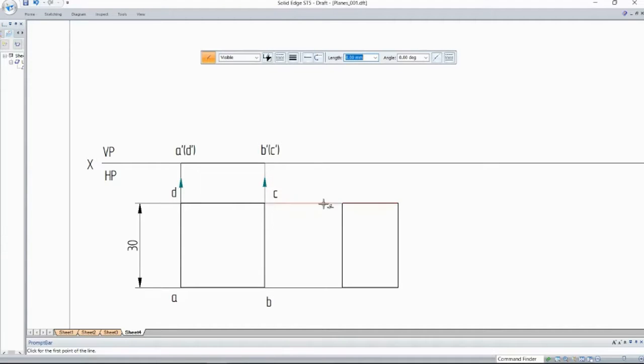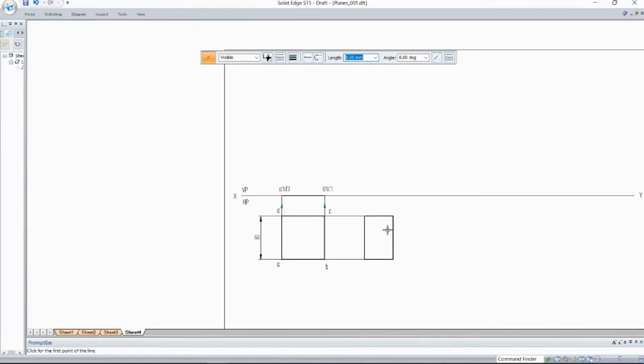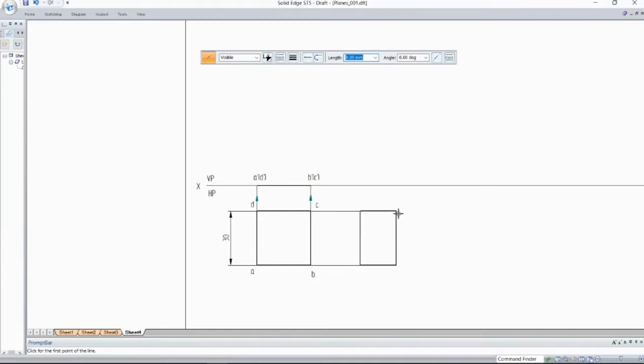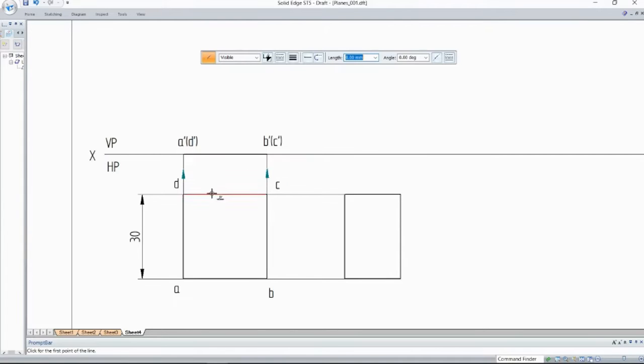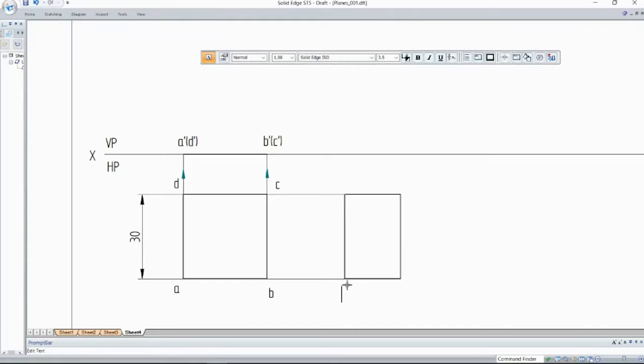In line with this, first you draw these projection lines. Then from this end, don't draw it too far away, because you need to draw the side view also, and the third step, the final view also. So just draw this projection line, then join this and obtain a rectangle of 30 into 20. Once you do this, let's name it. This end is A, and this end is B.